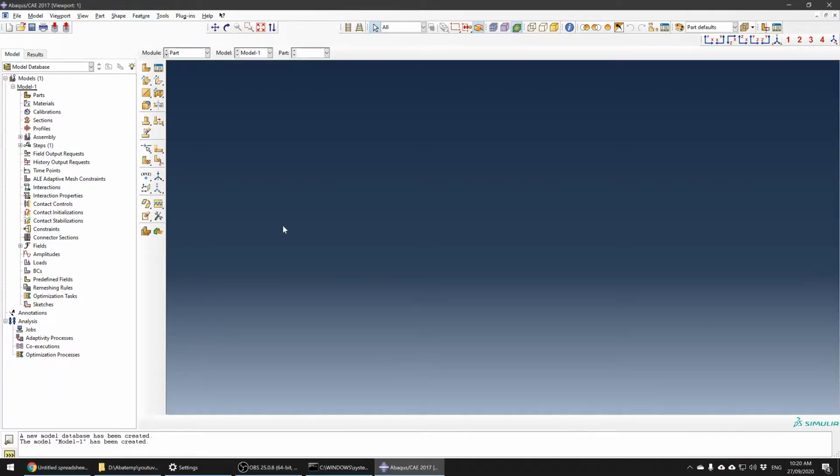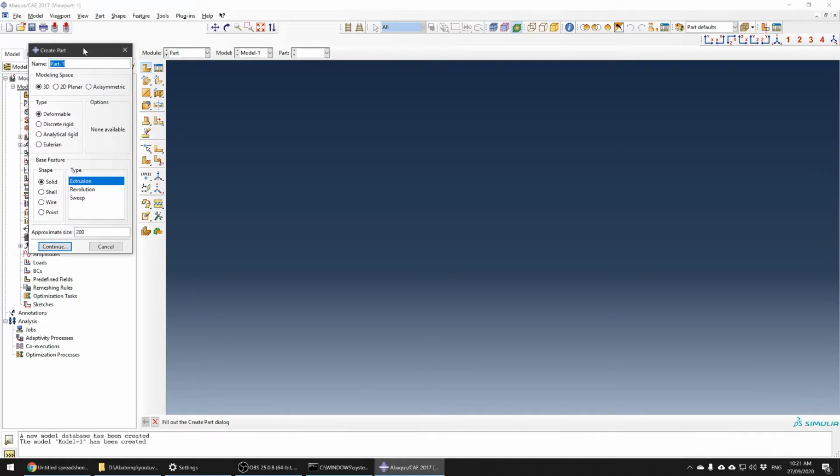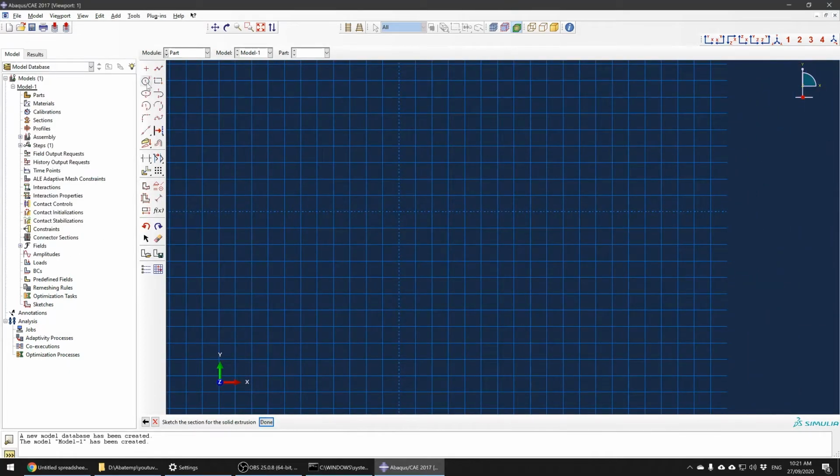All right. So let's start by opening your ABAQUS, and then you go to the part module. For simplicity today, I'm going to model it using a cylindrical solid element. So you click here, create part. This video is supposed to be a moderate level video, so if you don't know how to make a part, go check my other videos, all right? Because I will not explain in detail here the 3D deformable solid, because we want to make a cylindrical solid. And then you choose create circle, click here, and then put in some dimension.